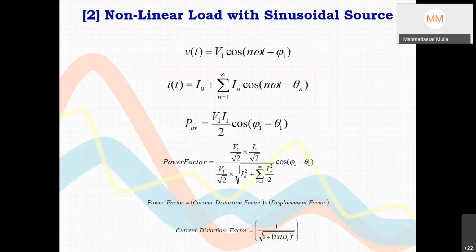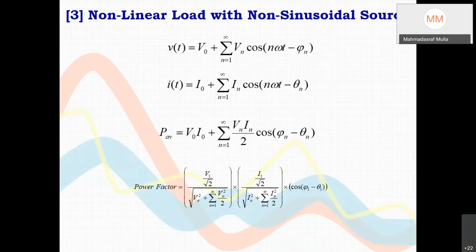And finally, this distributed generation voltage itself is having harmonics now. So then power transfer will reduce because of non-sine nature of current. It will reduce, and the phase displacement between fundamental voltage and fundamental current can also create this.